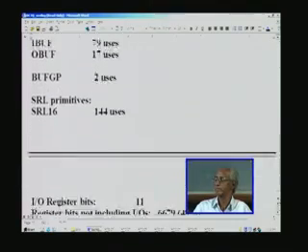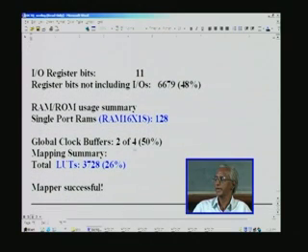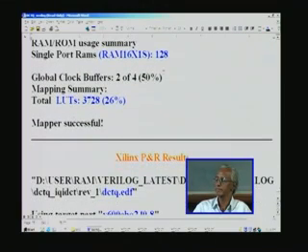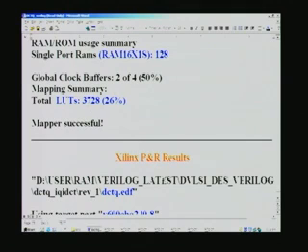Then it has taken 16 by 1 RAMs, 128 in number, and it has taken 3728 LUTs, which is roughly 25% of a 600,000 gate capacity FPGA, and in Xilinx we will have a little more optimization here, maybe 3200 here, and this may remain same.